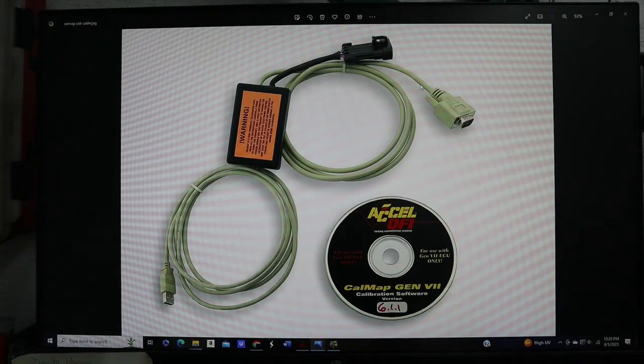What we used to do is have a little AM transistor radio, and you'd go by the car, and if it got static, then you had RFI problems. That's the only way I knew of testing them. If you have connectivity problems, look for bad grounds, poor grounds, the engine to the chassis, plug wires that weren't crimped properly, stuff like that. Anything that's got an electric motor that turns can create noise. So just be aware of that.